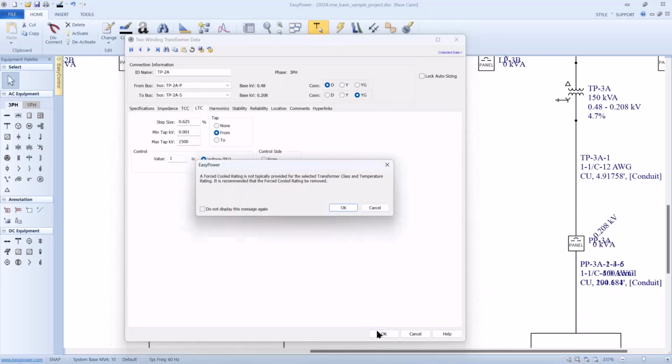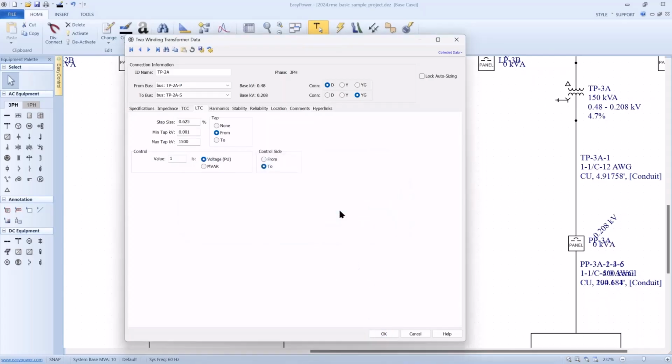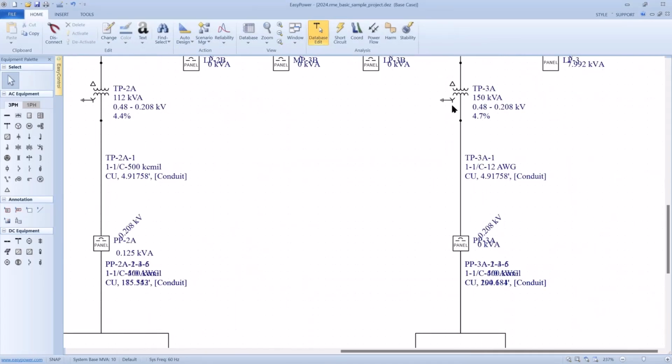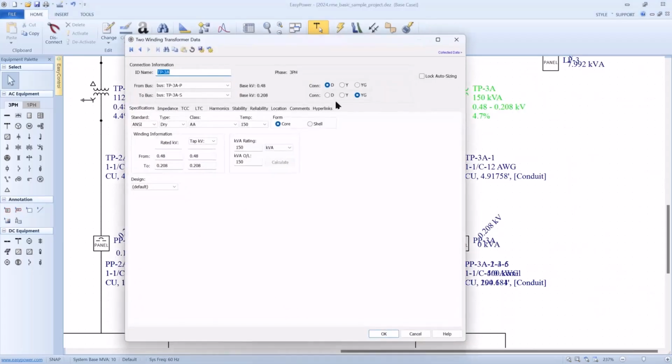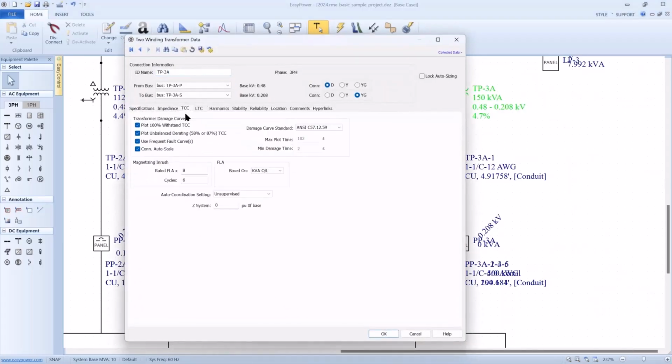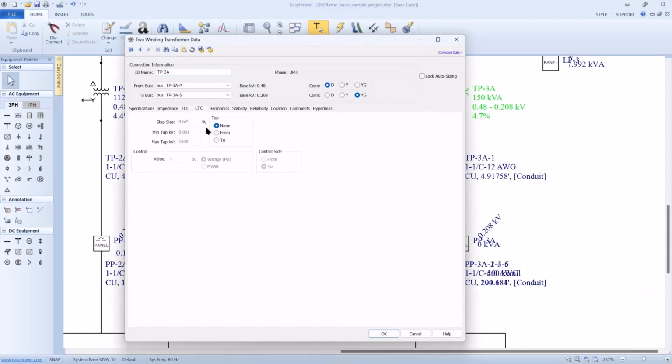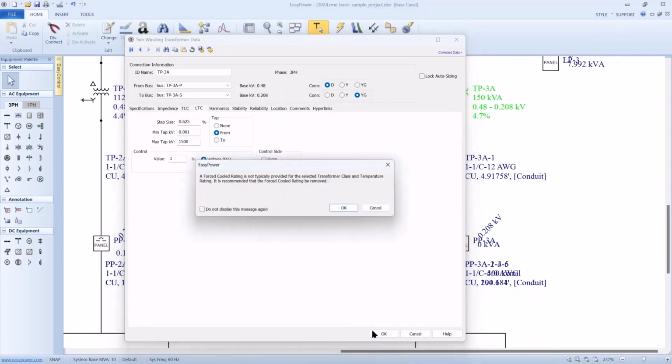And so by doing so, it's going to come up with the calculations for taps recommended based upon my power flow. Same thing we're going to do here. We're going to assume that there's a load tap changer and what it should be set up. And then this will give us what the taps are that we need to make as fixed elements.